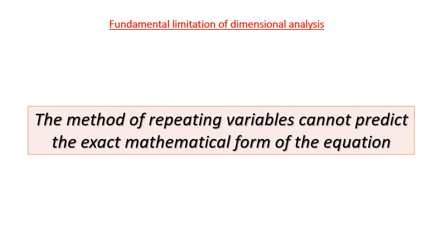Limitation for using dimensional analysis: the method of repeating variables cannot predict the exact mathematical form of the equation. So if you are going for dimensional analysis, you cannot get the equation, but we get the dimensionless terms. The major disadvantage is that we cannot obtain the relations between these terms, but we get the dimensionless groups.